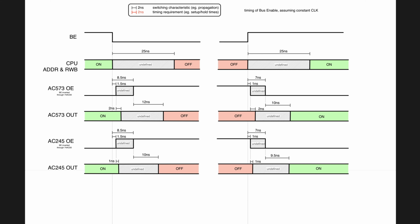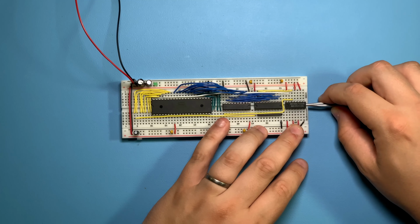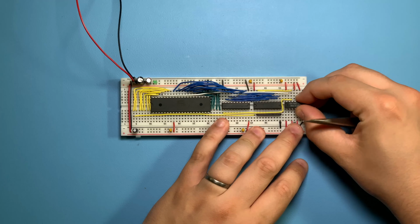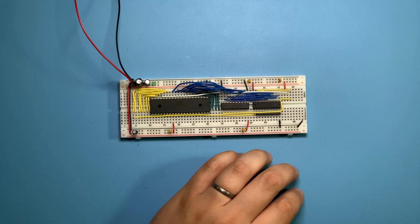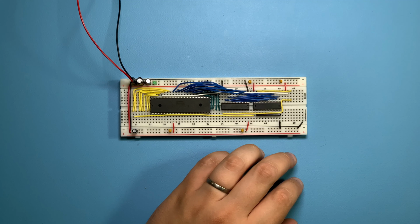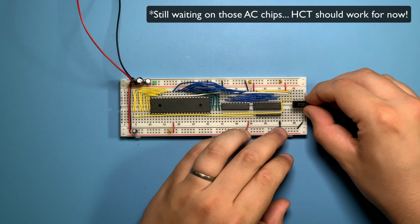Okay, so now we have everything specified. Let's build it on a breadboard. I'm going to remove the inverter and all the inputs that we forced high. And I'm going to replace it with a 74HCT00, which is a quad NAND chip.